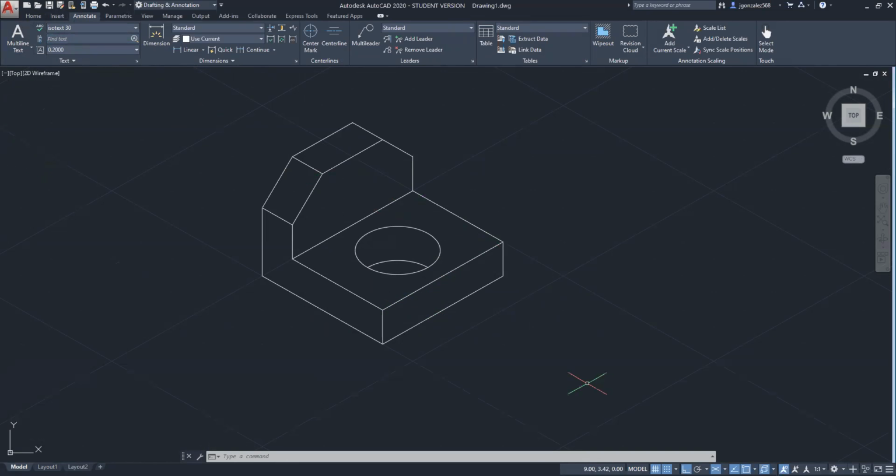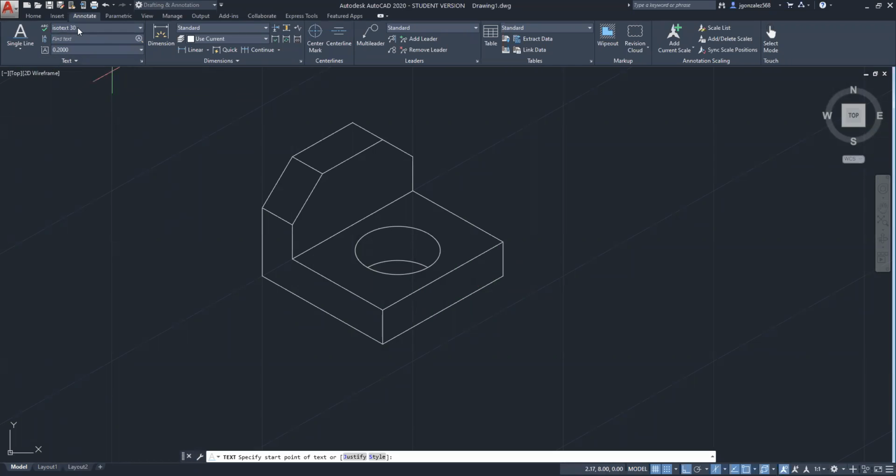Okay. So what I want you to do to draw on the front of this is to switch to the right perspective. So now I have this cursor along the wall of this front part. This is my right side. So I'm going to choose single line text, make sure that I have ISO text 30, and hope that this comes out.